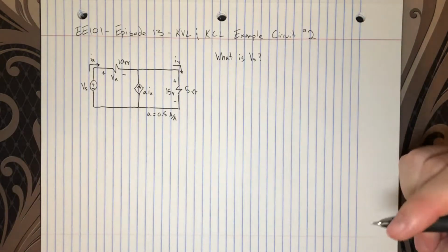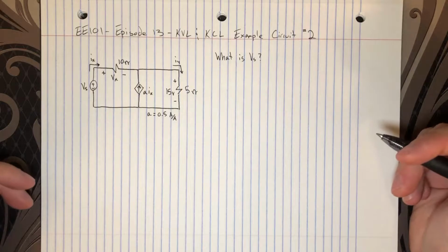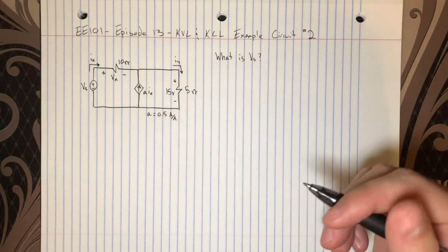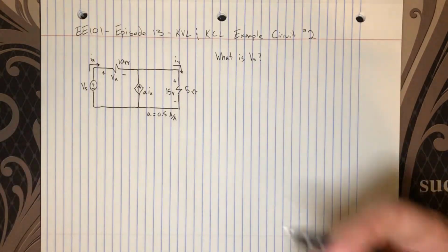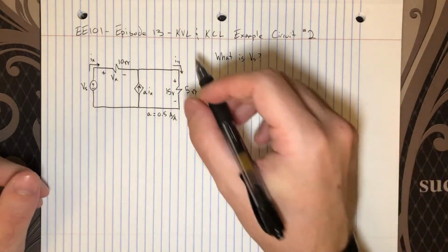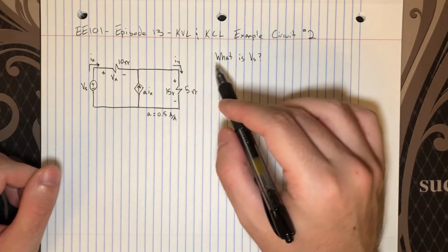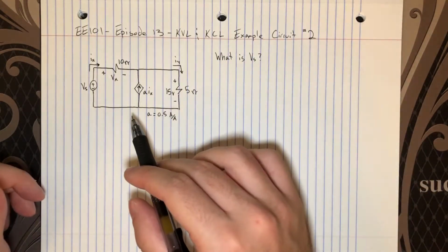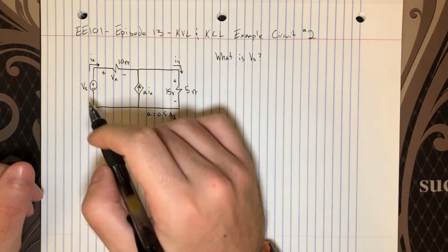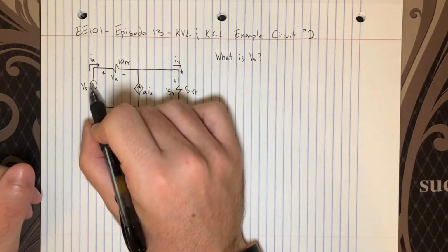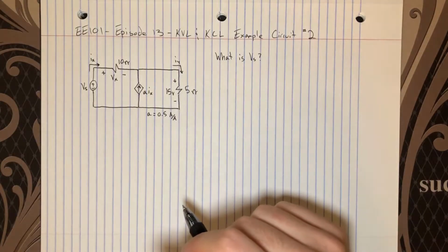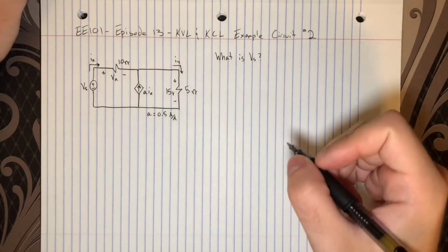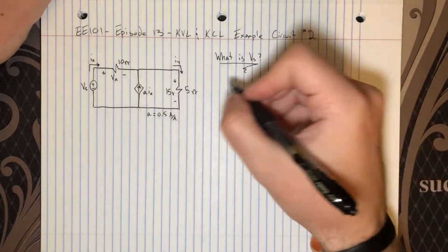So the first thing that I would do analyzing this problem is just ask yourself, okay, what's being asked of me? I'm being asked to find a voltage. So it's probably natural that you might want to use Kirchhoff's voltage law as a starting point. And if you think about it, we have Vs here, and with this polarity indicated by its plus minus terminals. So I'm going to employ Kirchhoff's voltage law here and write an expression for Vs in terms of some other voltages in this circuit.